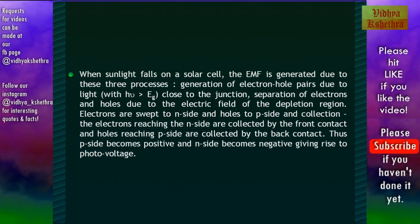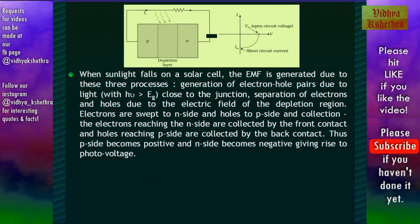When sunlight falls on a solar cell, the EMF is generated due to these three processes. That is, generation of electron-hole pairs due to light close to the junction, separation of electrons and holes due to the electric field of the depletion region, where electrons are swept to the N side and holes to the P side, and collection. That is, the electrons reaching the N side are collected by the front contact and holes reaching the P side are collected by the back contact. Thus, the P side becomes positive and the N side becomes negative, giving rise to photovoltage.